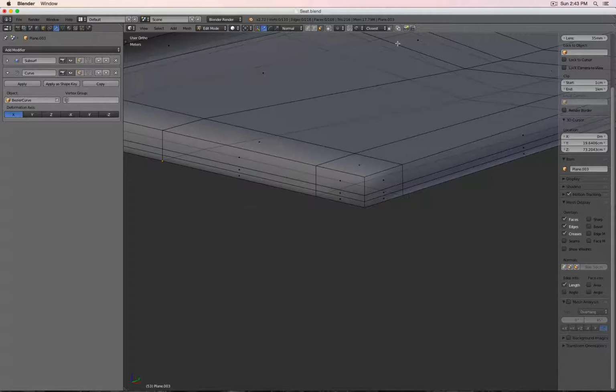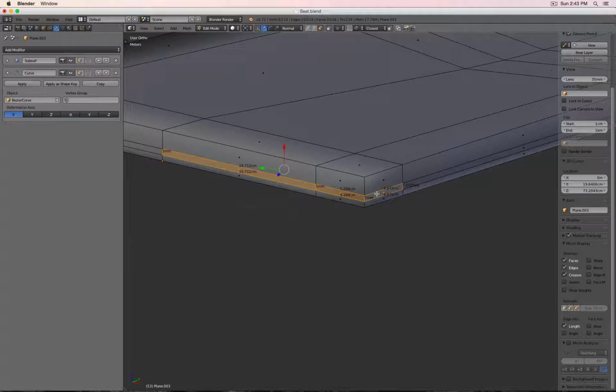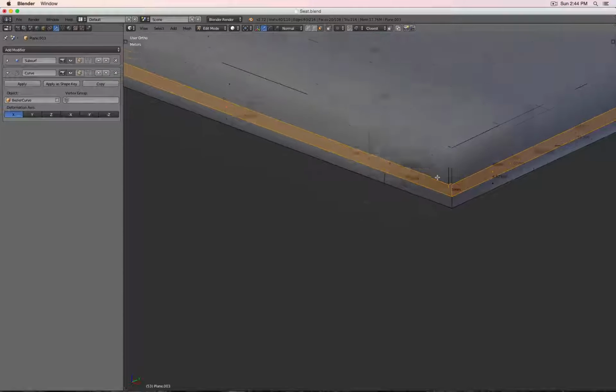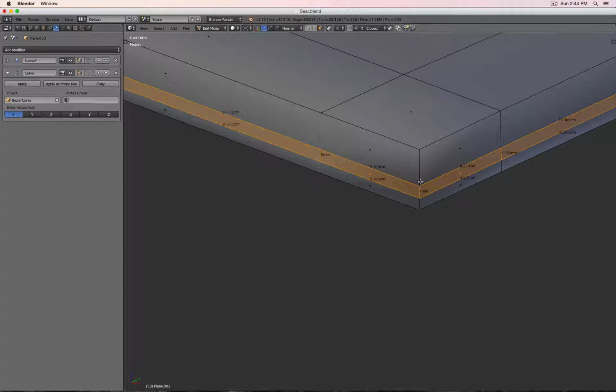And then I'm going to select all those ring faces. And with all these faces selected, what I'm going to do is simply extrude another kind of like, yeah, pipe out of this. So I press spacebar and type in solidify.